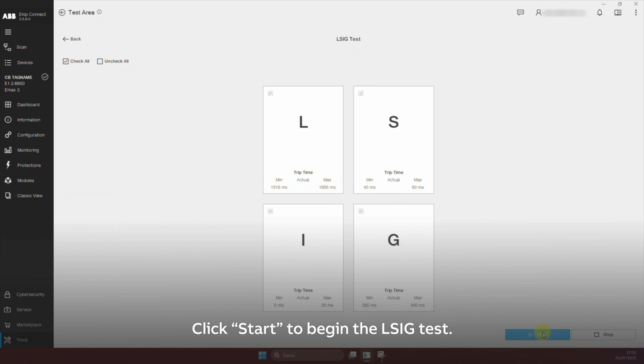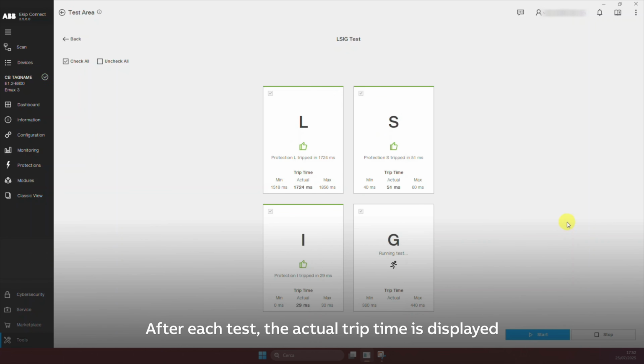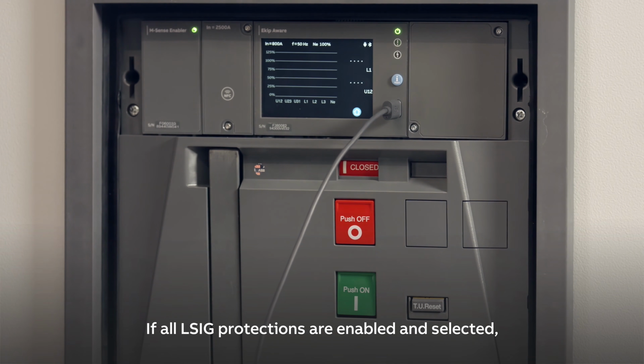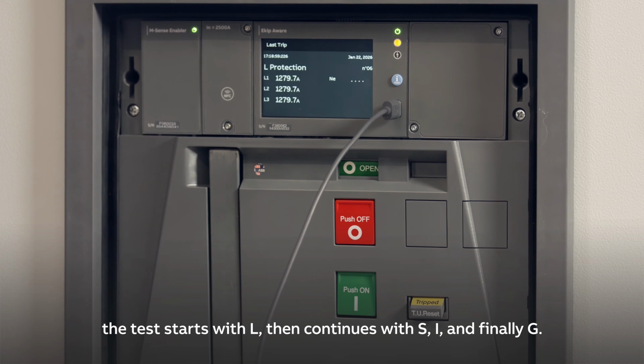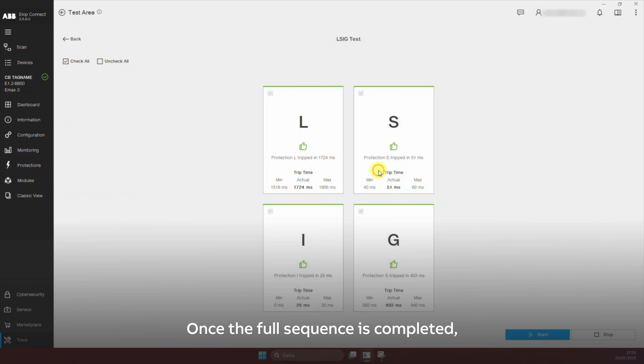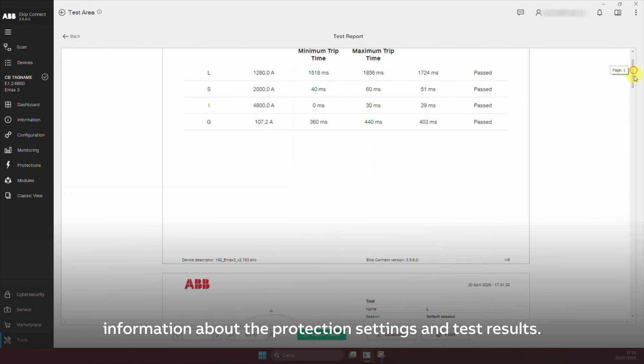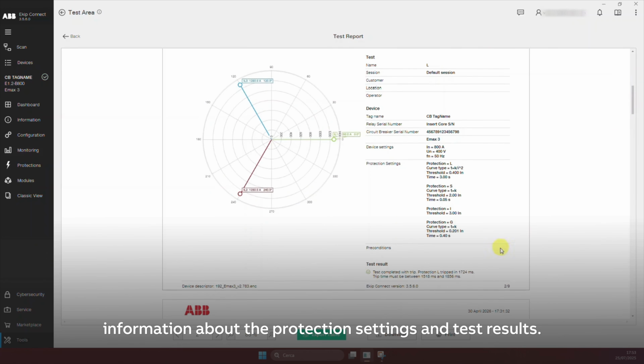Click Start to begin the LSIG test. The procedure runs sequentially. After each test, the actual trip time is displayed and automatically validated in real time. If all LSIG protections are enabled and selected, the test starts with L, then continues with S, I, and finally G. Once the full sequence is completed, you can generate a test report containing all relevant information about the protection settings and test results.